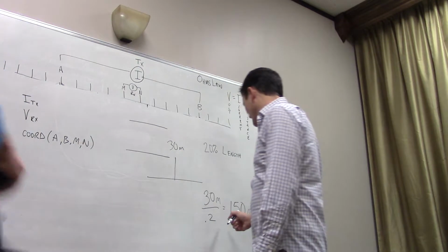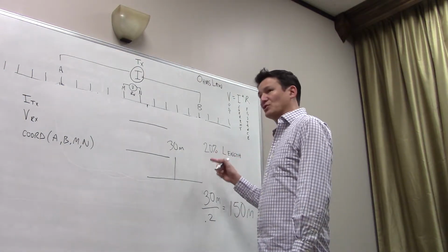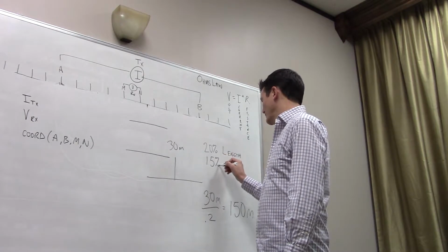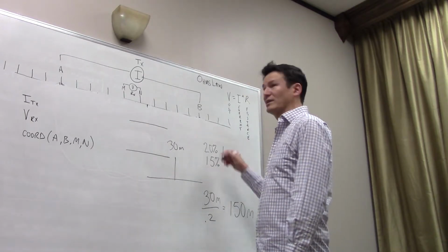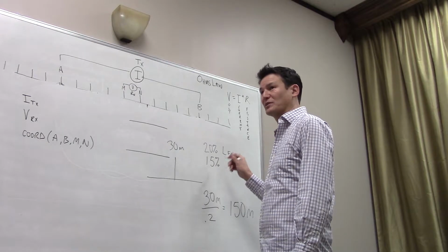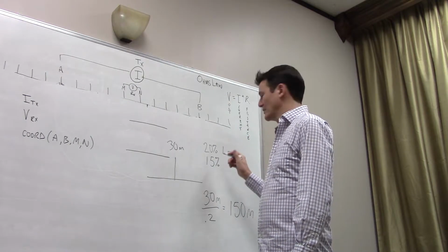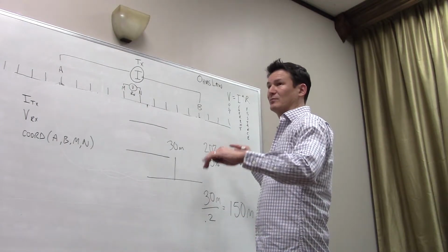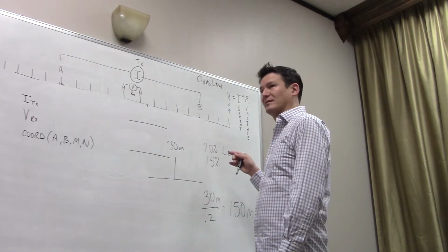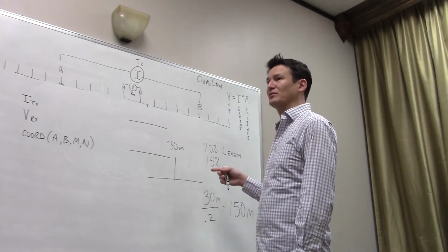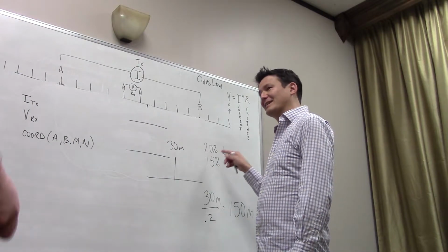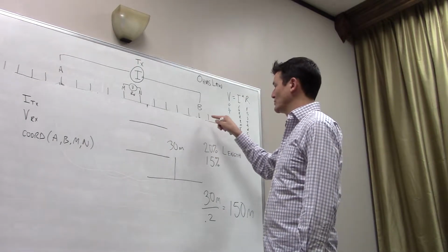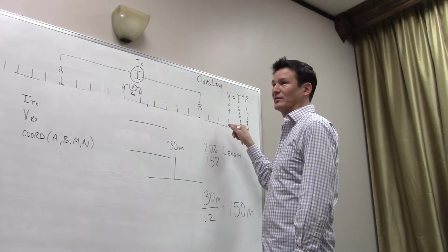And really, what I try to tell clients is that because there's noise and things like that, I try to be more realistic here with 15%. You may get more or less, but the 15% I know from experience, anywhere in the world you always get. The 20%, because you're separating the transmitter and receiver, you get more susceptible to noise. In some areas it's easy to do 20%, in some it's more difficult. So a lot of this, the depth of penetration and the quality of the data, has a lot to do with how well you prep the connection to the ground.